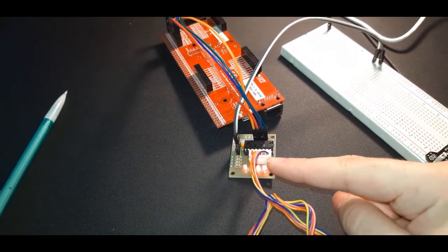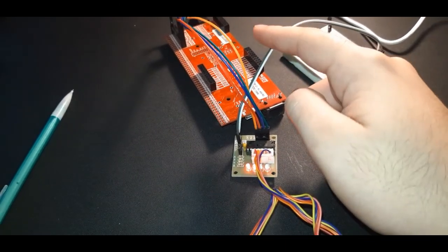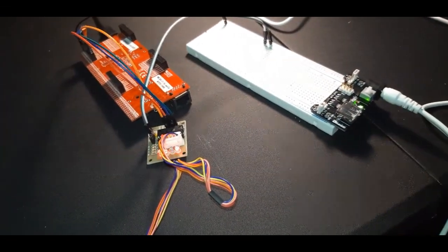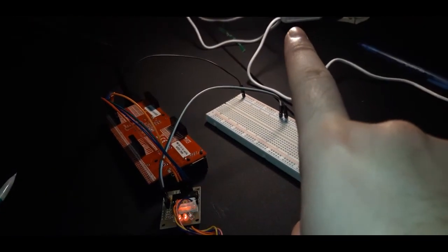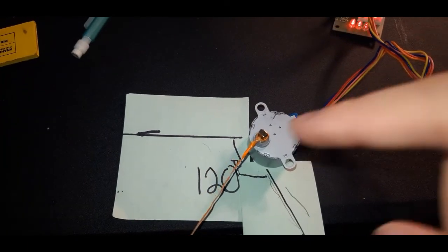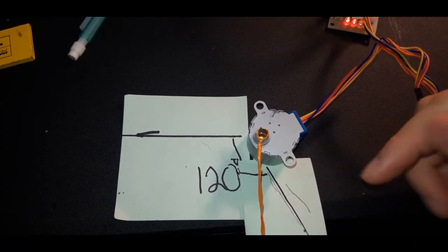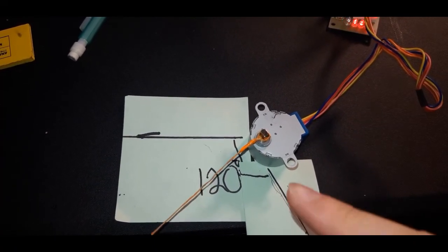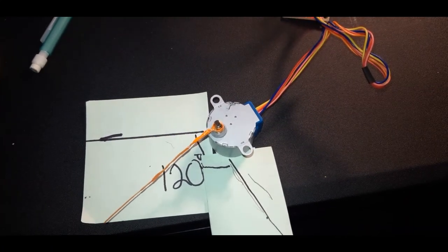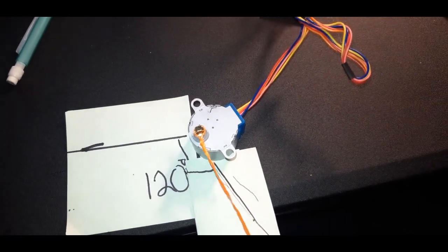Okay, I have my stepper motor, the driver module, my Tiva board here, the breadboard, and the power supply module, which is connected to the power supply over there. One more thing to note is that in this experiment, experiment 3, this is the motor that has the medium torque, the smallest step angle, and it's the 1 or 2 phase at a time. So it's basically the half step one.